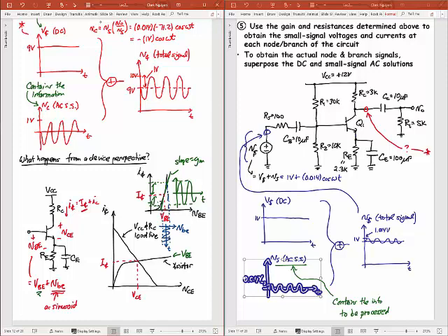Okay, and then around here, I'm going to do exactly the same thing that I was doing before. I'm going to wiggle, this time, IC, because VBE wiggled IC. And so IC is wiggling here. Maybe I'll show it like that, and then coming down like that. And so in actuality, IC wiggles like this, and that causes a wiggle in VCE as well. But actually, I'm not doing this right, so let me fix this a bit. This is not entirely correct.